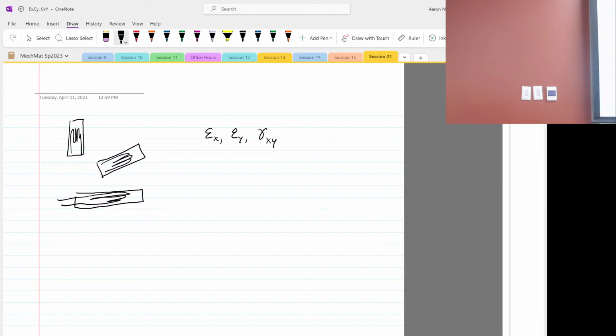Shear stress is along the longitudinal axis. But if I take an element that is on the longitudinal axis and on the face, so I take a slice, they're on the same element. So they're the same. And the transverse shear stress on that face ends up being the same as on the longitudinal axis, or in the longitudinal direction.